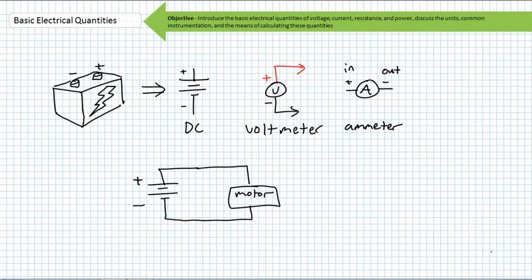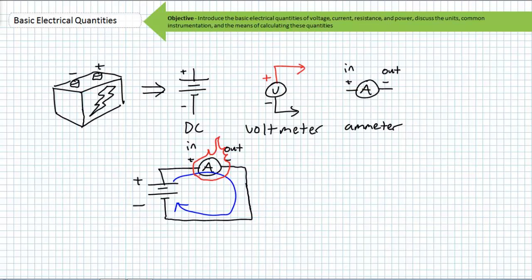To measure current in an electrical circuit, the ammeter must be inserted into the circuit. Additionally, the circuit must have a load in it, or an opposition, for current to be controlled. If the load wasn't in there, the current would be uncontrolled, and your ammeter would just start on fire, and you'd spend the rest of the day in the hospital getting your lab instructor's boot surgically extracted from your backside.